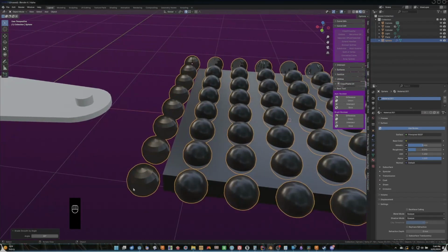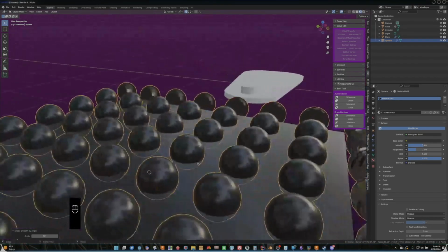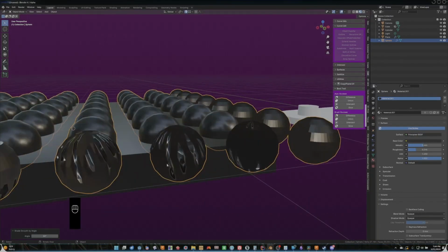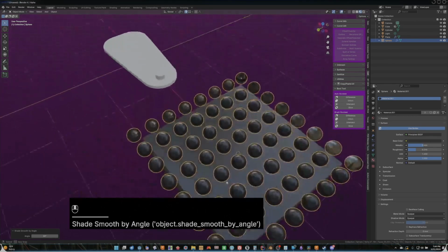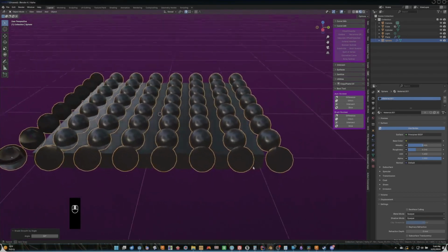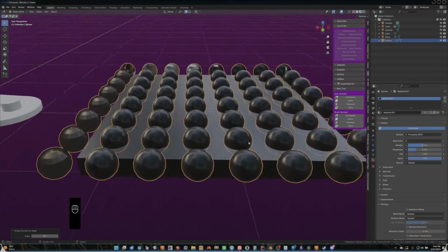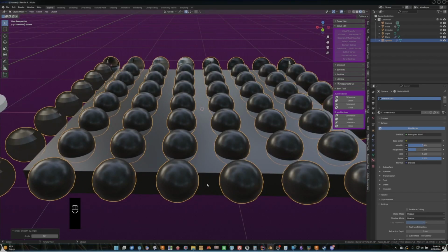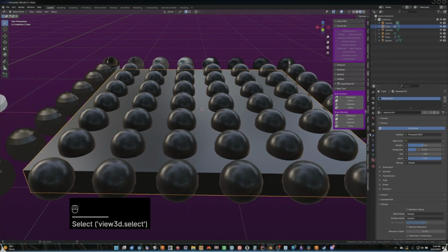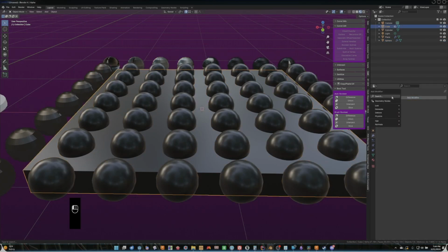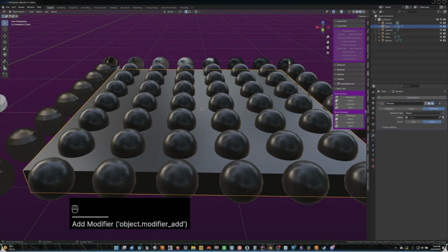That'll give a nice effect to it later on. Although I'm uncertain why these objects got weird flat shading and these objects got smooth and these objects are just wrong. I don't know what's happening. In any case, I'm not going to stress about that right now. We'll cover that at a later time. All the spheres that are going to affect our little surface here, they are all the right shading. So we'll go ahead and create a Boolean on our surface we want to affect. And Boolean, and then we're going to select these spheres.